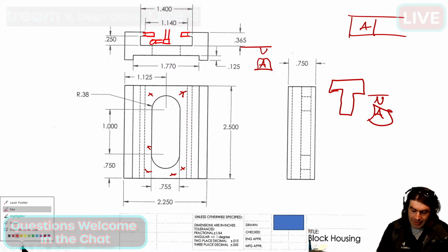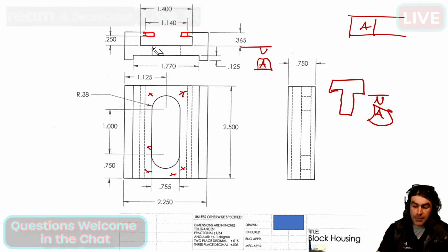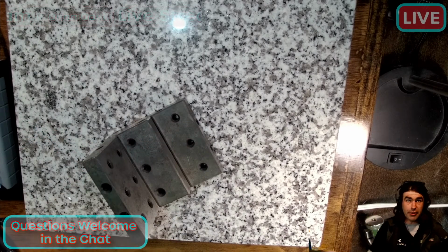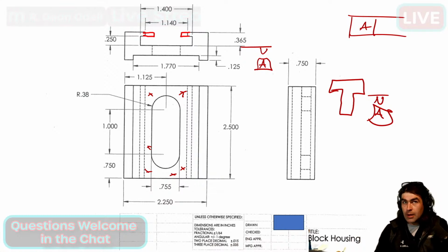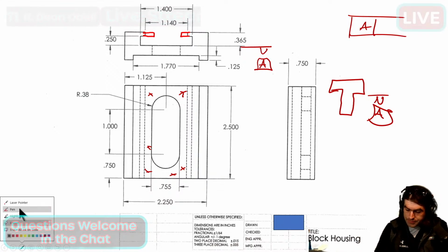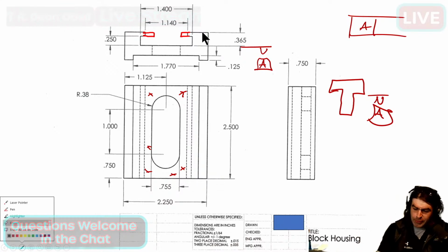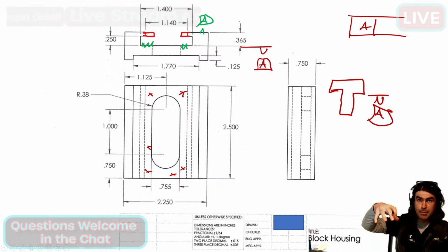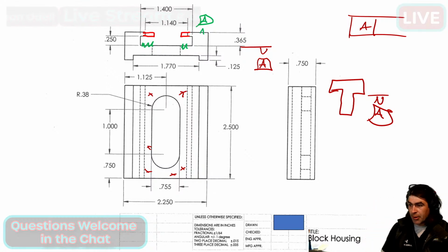All right, so that makes it an inconvenient datum for a CMM. Also, not super easy to measure on a surface plate, like a granite plate with metal stuff, right? So, say we did have this overhang. Even if this is the functional feature, we would probably want to make something else datum A, right? Because it's going to be the thing we could put the part on.